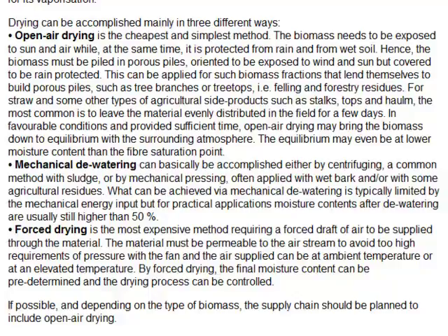So it is only applicable to very wet materials. But it is cheaper than forced drying, and it is very much faster than open air drying. So mechanical dewatering can in some cases have a role to fill.